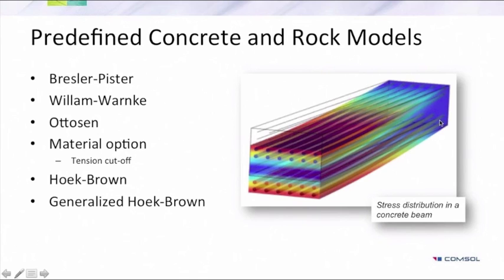Here you connect 2 different types of elements. The bars are modeled with truss elements, which can only take axial stress, while the 3D elements, which are modeling the concrete, can take stresses and strains in different directions. But with COMSOL, you can connect those different types of elements since they share nodes, and you can get the accurate stress description in both types of materials.